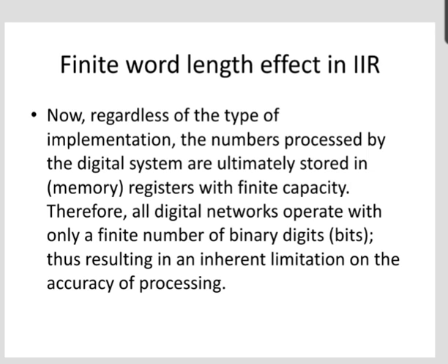When signal is sampled or calculation in a computer is performed, the result must be placed in a register or memory location of fixed bit length. Rounding the values to the required size introduces an error in the sampling or calculation equal to the value of the lost bits, creating a nonlinear effect. Round off error is a characteristic of computer hardware.